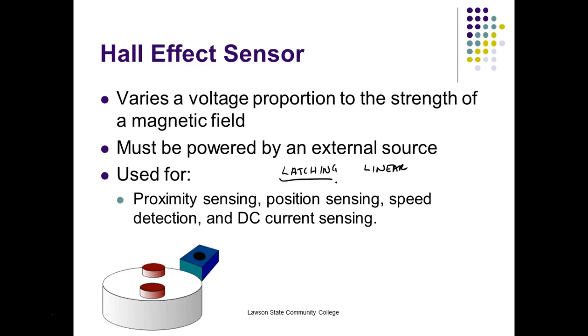One polarity, one field, will cause the output to turn on, and then you can take the field away and it would stay on forever. You could bring the same field in there, like the north, and it would stay on. For it to turn off, you have to give it the opposite field. So north might turn it on and latch it, and south would turn it off.